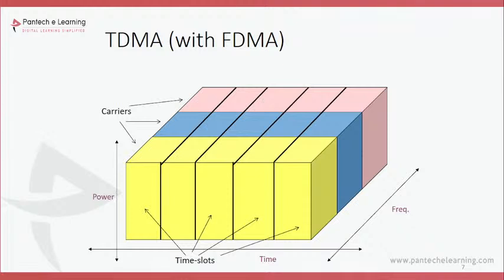The individual mobile stations are cyclically assigned a frequency for the exclusive use of a time interval. In most cases, the entire system bandwidth for the interval of time is not assigned to a station. However, the frequency of the system is divided into subbands, and TDMA is used for multiple access in each subband.